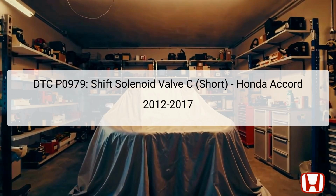The Diagnostic Trouble Code DTC P0979 indicates a short circuit issue with Shift Solenoid Valve C in the Honda Accord models between 2012 and 2017. The role of the Shift Solenoid Valve C is pivotal as it controls the hydraulic pressure supplied to the clutch system, impacting smooth gear transitions.